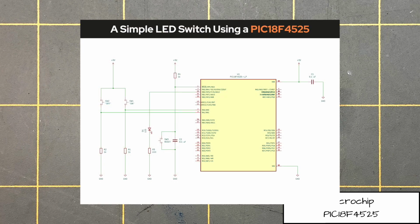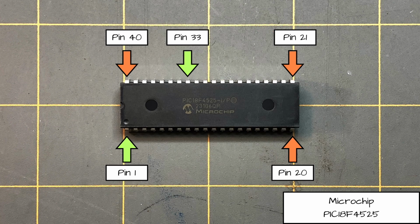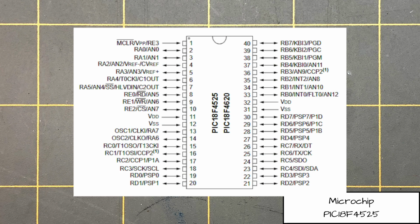So when the switch, switch 3, has not been pressed, the MCLR pin is held high via the 1 kilo ohm resistor, that's resistor R4. Once the push button reset switch, switch 3, is pressed, it takes 5 time constants for the capacitor to fully charge. Looking at page 2 of the data sheet for the PIC 18F4525, we can see the pin diagram. Pins 2 and 3 are contained in port A of the microcontroller. Pin 2 is referred to as RA0, and pin 3 is referred to as RA1.